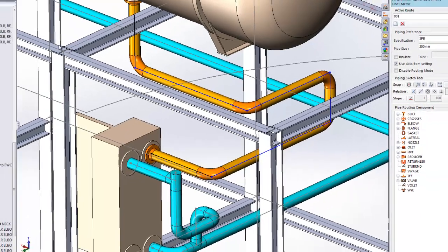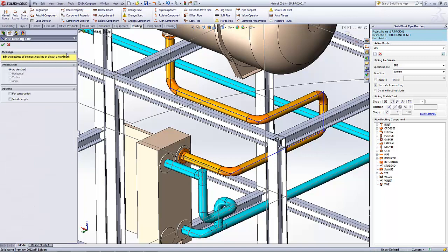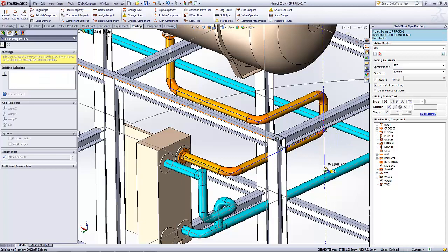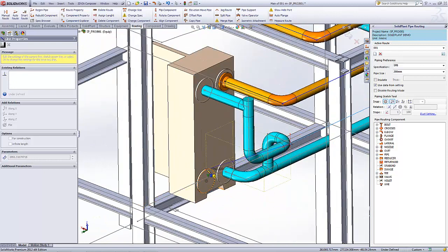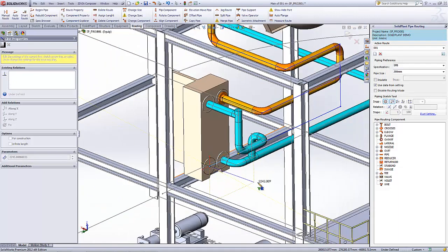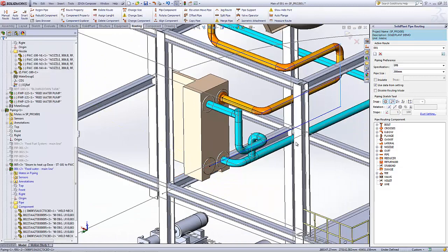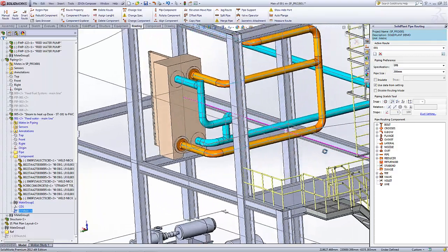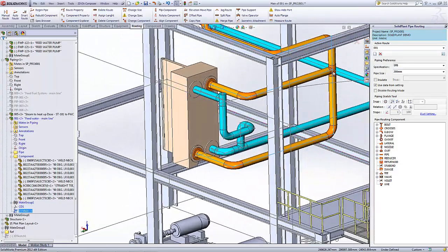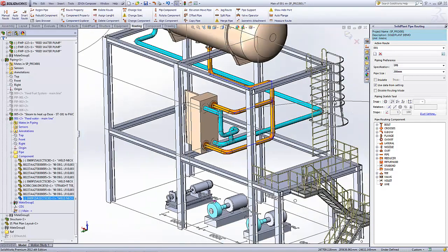Now we are going to show you the smart fitting. We press again on the manual route button and we click on the elbow. We design another line, then we snap center along X and into the center of the nozzle. Automatically the system creates the pipe with new features. Instead of the elbow, we see now a T is created. We move it and the system reveals itself.